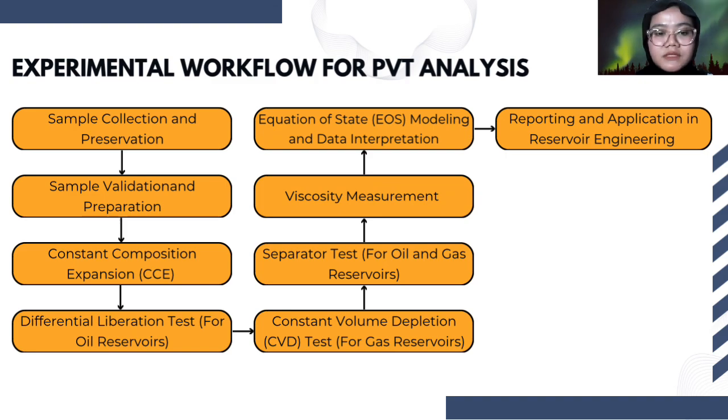Next, viscosity is measured to understand its flow characteristics. Next, equation of state modeling and data interpretation. The collected data is used to create a thermodynamic model that predicts reservoir fluid behavior. The last one is reporting and application in reservoir engineering to optimize reservoir management and production strategies.